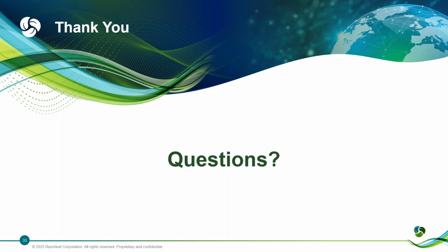Okay, and if anyone has any additional questions, please just drop them right in the chat box. And it looks like I have one more, Kip. Can you create multiple mBOMs against an engineering BOM? Yeah, so you may have multiple plants that you're gonna do production at, right? So this is where plant specific comes in. So you may end up doing multiple mBOMs from an engineering 100% BOM based on a specific plant. So it is possible that you can do it. It just takes a little bit more planning and structure and things like that.